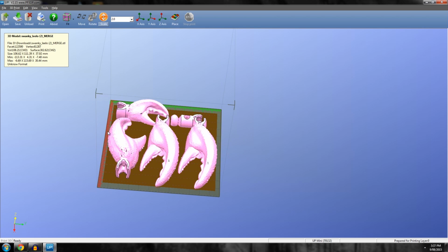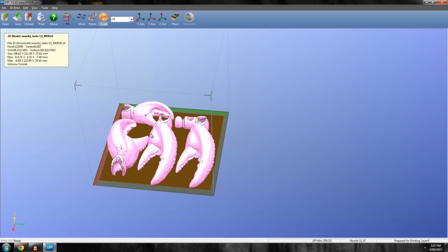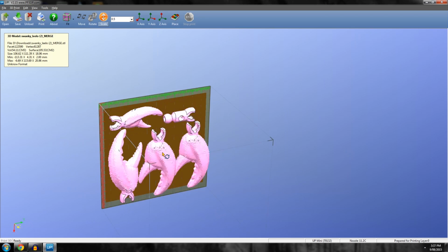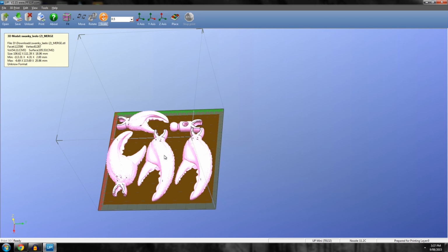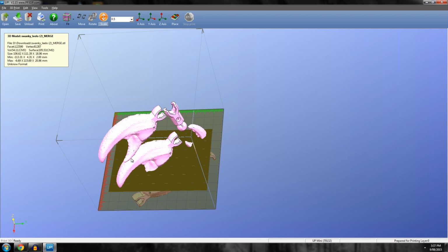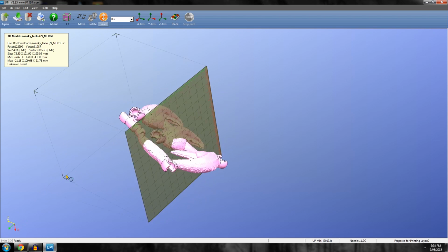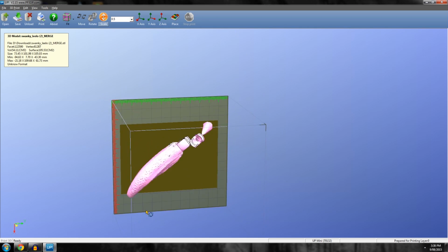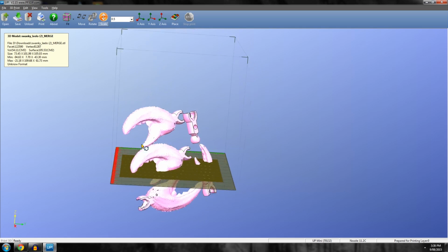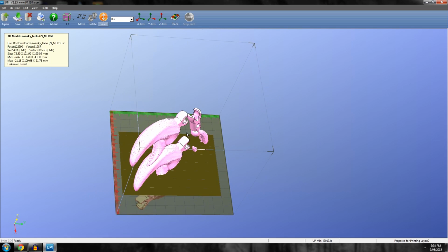And something that's really limiting in the Up software, there's no undo. So Control Z doesn't do anything. You're screwed. So I have to enter 0.5 and then do it again to return it to normal. And this applies for everything. So if I accidentally rotate this around by holding Alt and spinning it, which is not handy at all, I can't undo that. So that's one major disadvantage of the Up software, but it's just something as you use it, you'll get used to trying not to do.